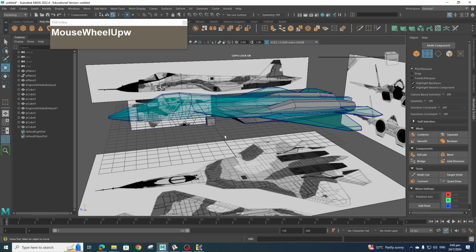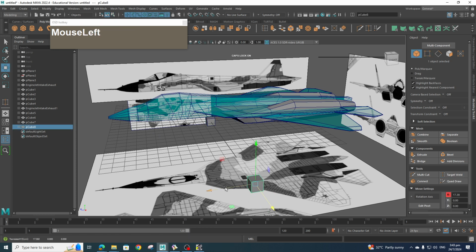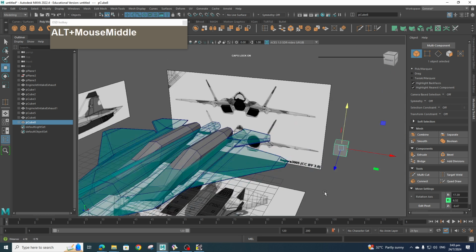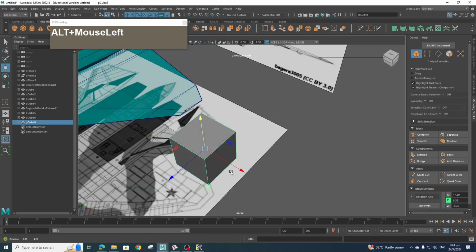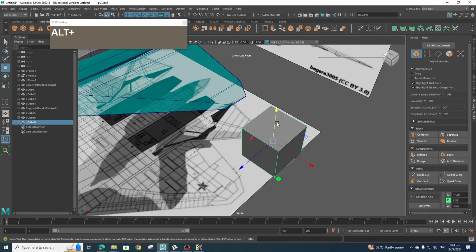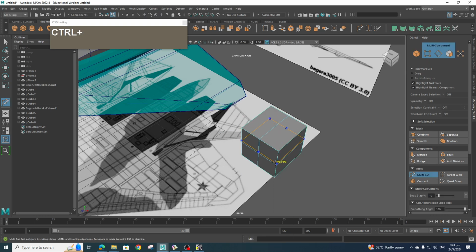Okay, I'm creating another cube. This will be my vertical stabilizer. So same thing, it's very easy to create the aerodynamic cross section. This one we'll do vertically. So same thing, we just use a multi-cut here, and maybe one more right about here.